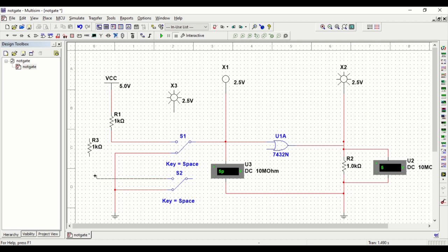So this is the OR gate, the truth table for the OR gate, which we're going to present at the end, is a truth table that requires any of the inputs to go high for the output to go high, and when all inputs are low, the output should be low.